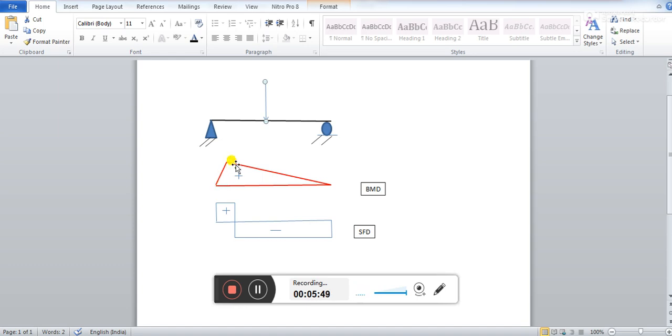The moment diagram will change, and you see this bending moment diagram will become triangular in shape. It will also be triangular, and the peak point of the triangle will be here, right? Just at the bottom of the load, right? Will it not be? Is it okay?